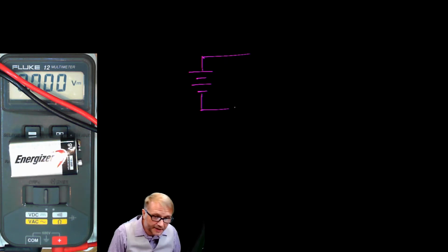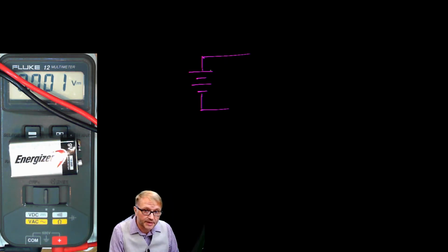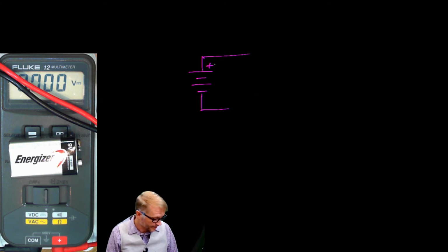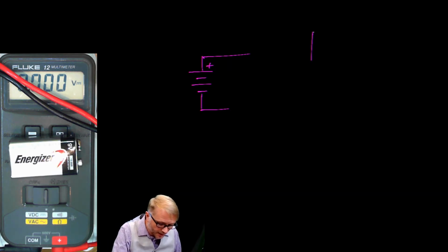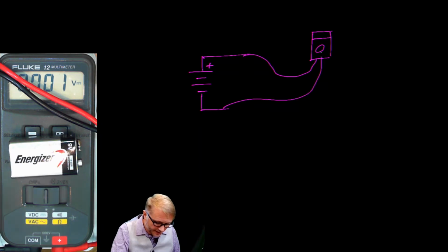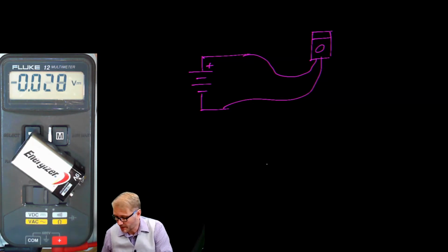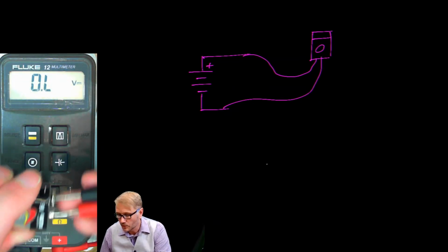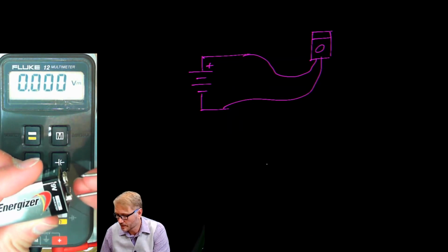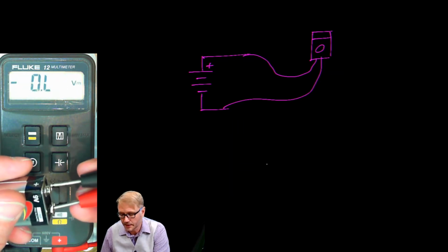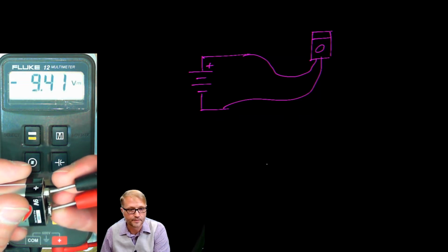By the way, schematically, the large bar on top is for the positive polarity. You could also put a little plus here if that helps. We had our voltmeter here, and we connected one lead up there, and we connected one lead there. And the voltmeter measured a positive voltage when we had it one direction. Right, so here we have positive. And if you flip the battery around, it will read a negative.